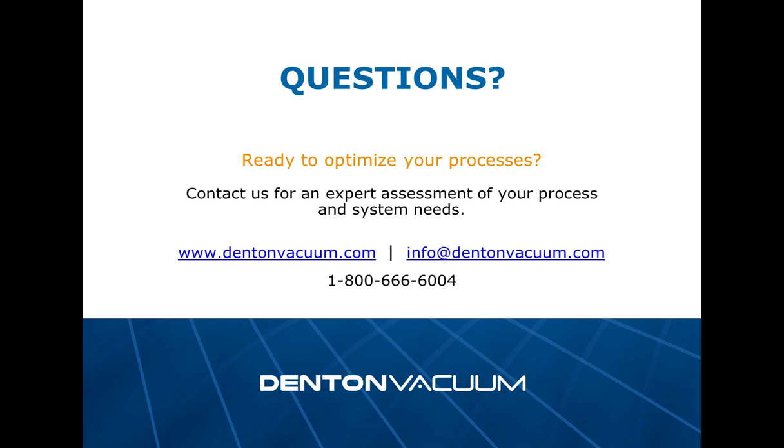For metallization layers, it's the same. The oxide removal is very critical, and ideally in situ is better than ex situ, although we do see some applications where an etch followed by deposition within a few minutes is sufficient. But for really low resistance metal contacts, you want to do any pre-clean in situ.